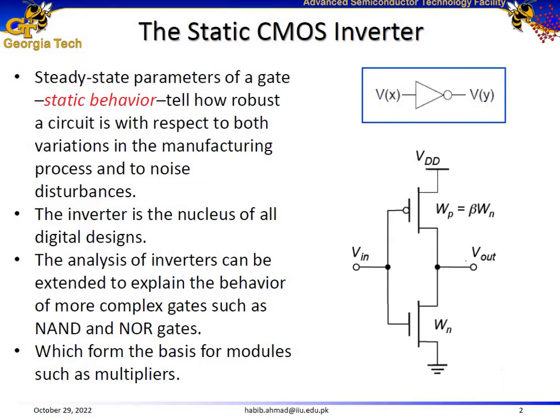Okay, so the reason is that we need to reverse bias the drain and the substrate so that the current does not leak from the drain to the substrate. If you apply positive voltage to the drain and a negative voltage to the substrate for an NMOS, then it is reverse bias, because what is the substrate for an NMOS? What is the bulk for an NMOS?